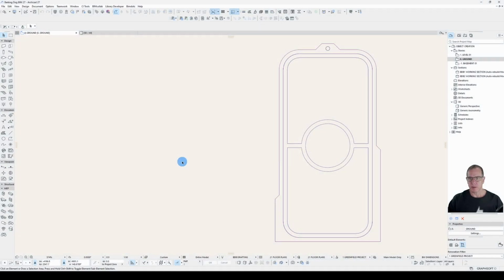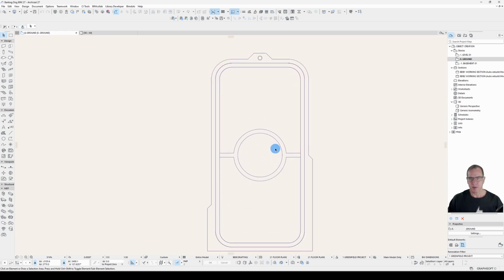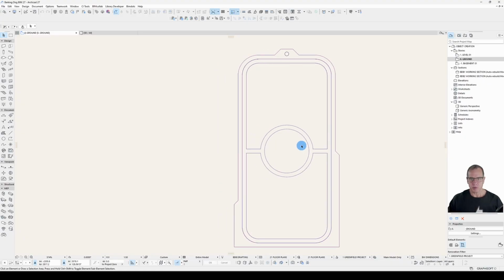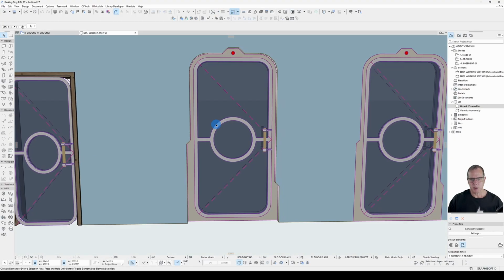We're just going to create the same door. This is my floor plan with the morph and walls and slab, etc. And remember that the door is lying face down on the floor. So we are looking at the inside face. So that means left and right are flipped. To confirm that, the high side is on the right as we're looking at it. In the external view of the door, the high side's on the left.